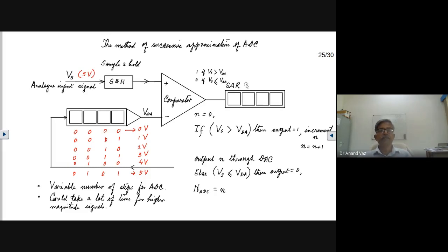And we take the analog signal, let us say this analog signal, we need to tell this circuit when to start. We have to tell the sample and hold when to start, and we have to tell this successive approximation register when the process is going to start. So for that, we need a start conversion signal. Okay. So we'll have to start the conversion. So you need a signal for starting the conversion. Start conversion.